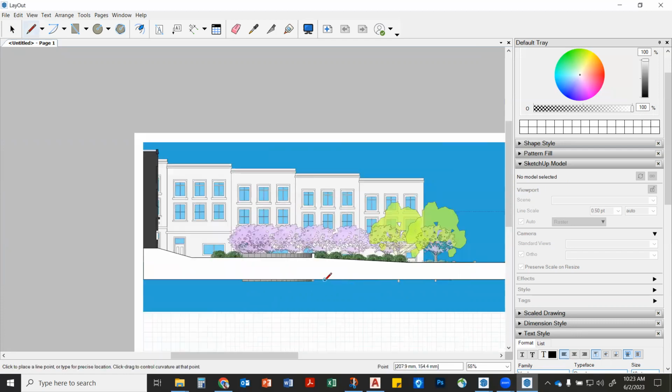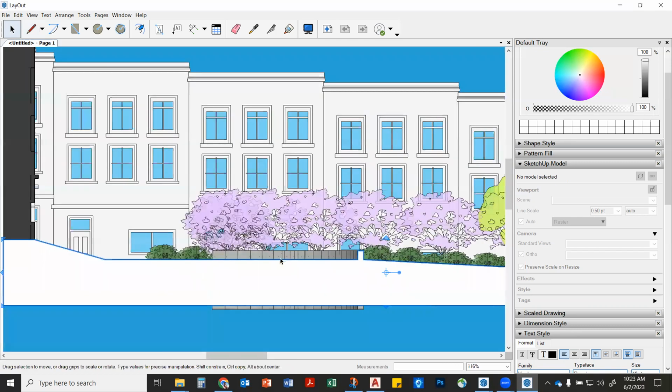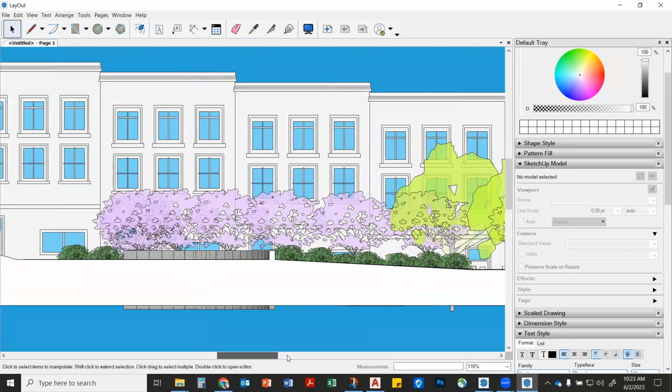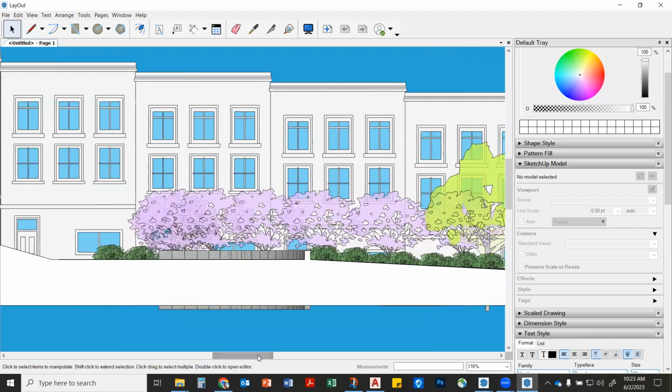Okay, isn't that great? Look at that. I knew you guys would like it. Just knew it. But isn't that nice? So now this clean section I can either diagram, and it's really easy to convey sections and stuff. And you can do dimensions in here and everything. Like you can actually grab this dimension. And the cool thing is your dimensions will read from the model, right? So I don't have to go in there and type them up every time.